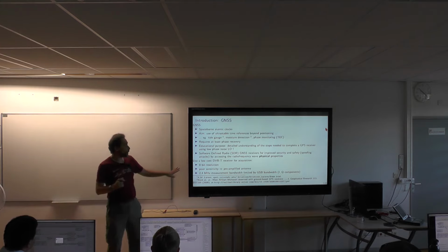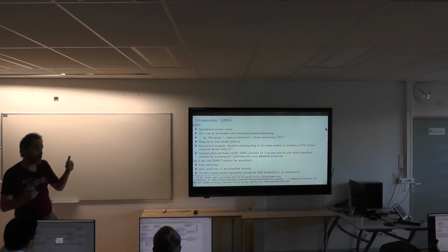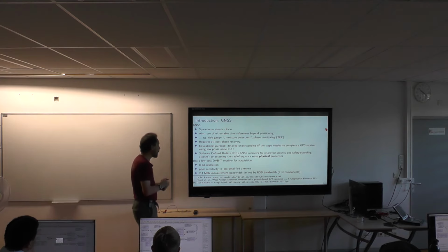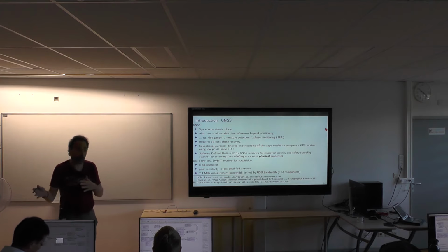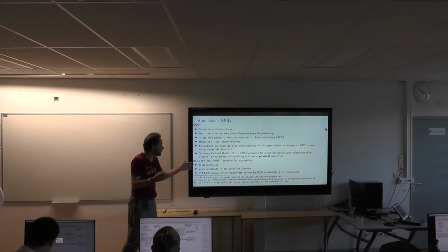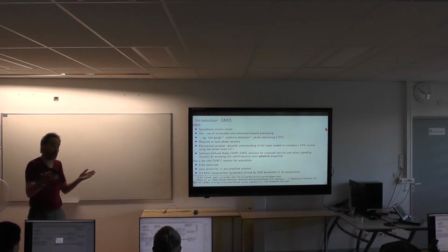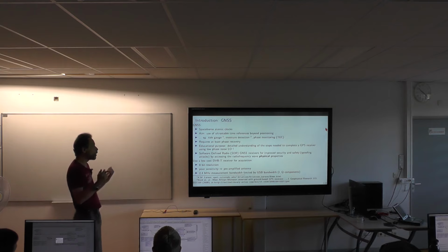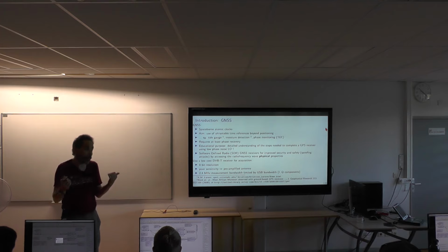These low-cost DVB-T receivers, why are they so low-cost? First of all, because they're initially sold as digital video broadcast terrestrial receivers, so they're consumer-grade electronics. Usually when you go to SDR, the cost rises with bandwidth and with resolution. Here we have rather medium quality 8-bit resolution, but that's more than enough for GNSS. Many GNSS receivers actually only work on 2 bits, because we're going to see that the signal is well below the thermal noise. So all you would do by having more bits is sample the noise.